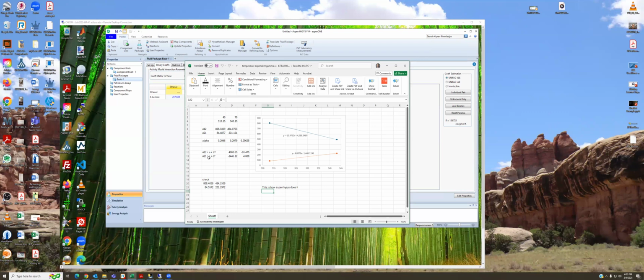And then here are those linear models. We're going to fit A12 to this dependence using the two A12 values at the two different temperatures, and A21 similarly to the two values at the two temperatures here. This little plot shows you that fit, the temperature dependence of the two parameters, A12 and A21. That gives us these four constants that we can put into the simulation.